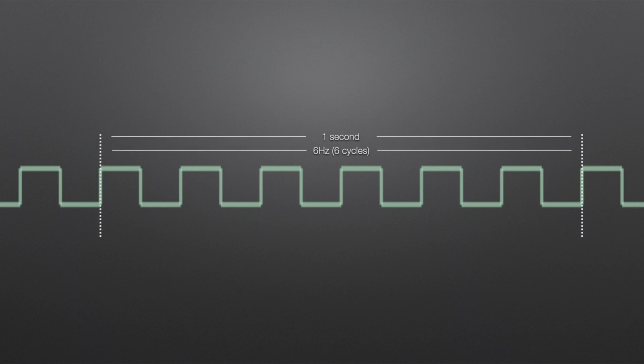I'm looking to create a consistent square wave at a rate of 6 cycles per second, 6 Hz, on a 50% duty ratio. That breaks down to roughly 167 milliseconds per cycle with a pulse width of 83 milliseconds. Our target amplitude is 12 volts, which is the standard voltage for pretty much everything in the computer.